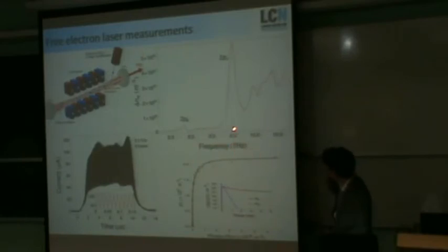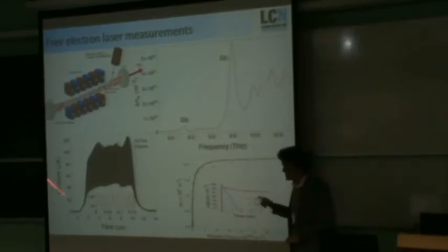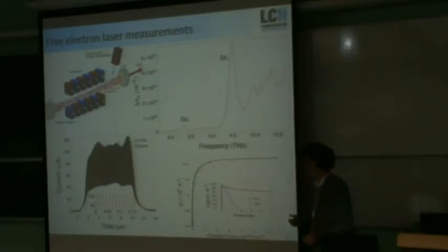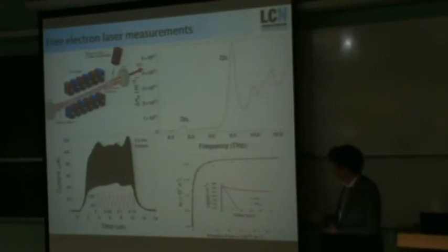The FTIR spectrum. But here what's interesting, if you stick on frequency, on resonance at this point, this is what you see here, you start to see a modulation occurring. Now what this is a result of is the free electron laser incident on the sample, which arrives in very short micropulses at a repetition rate of about 60 megahertz. So basically what you're seeing here is the sample being modulated at 60 megahertz. So I guess what we see here is that actually we've got quite a fast terahertz detector in the sample itself.